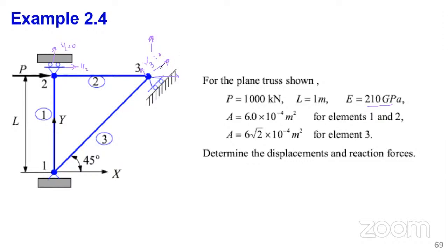As the support moves upwards, we are going to have a component of displacement, so V3 global is not equal to 0. Only, this support will not lift from the base, it's a roller. So that's why we are saying V3 prime is equal to 0. And this is a fact that you're going to utilize later on. You see how we are able to transform from the local coordinate system to the global coordinate system of what we know. This is a known condition.